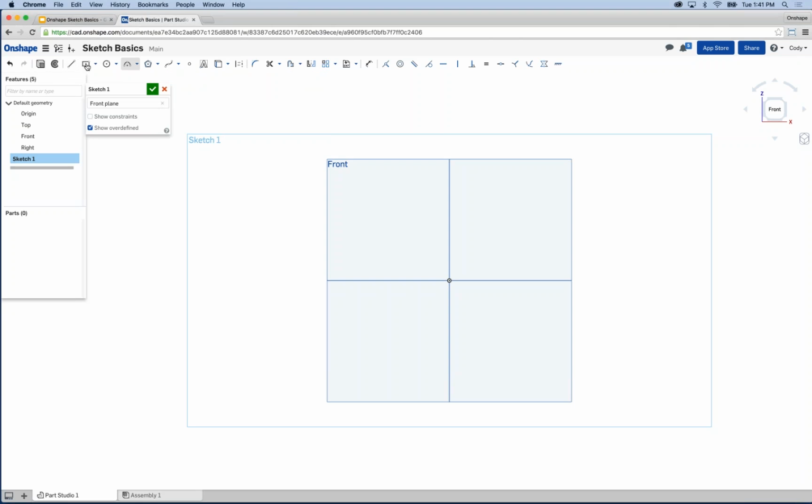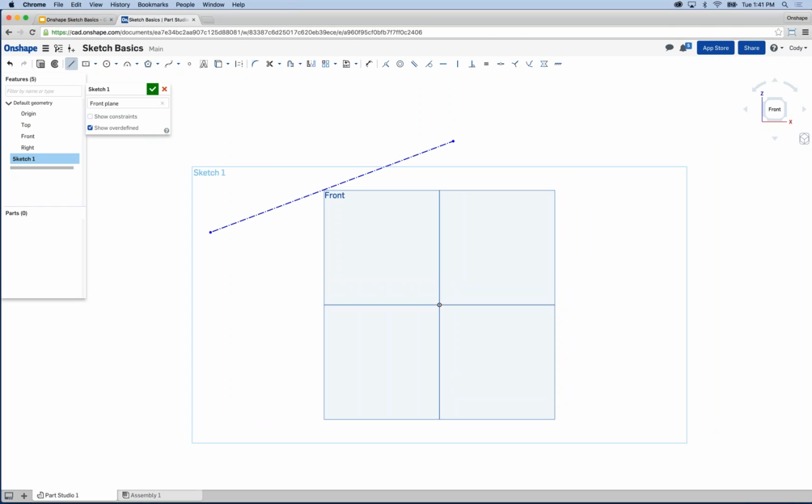Now you can select any geometry, lines, circles, rectangles, whatever it is. So I'll select a line, then click construction, okay? Then left click, and now I have my construction line. And it doesn't matter whether it's circles or arcs or any of those types of commands, you simply select the tool, then you select construction. Now the question often comes up, well, what if I already have a line? And the answer is you can convert entities to sketch geometry. Left click the geometry, left click the construction command. And that will convert existing sketch geometry into construction geometry. Okay.